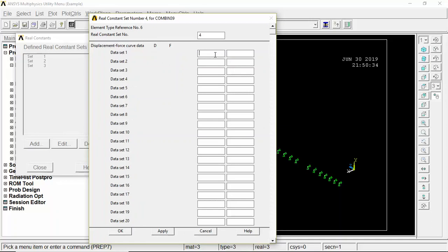You can refer to an experimental study where they, for example, draw the stress and strain and the shear stress for the bonding between concrete and steel, and you have to calculate those items, because there are stress and strain, and you have to transform the stress and strain to force and displacement, because you have a spring here.